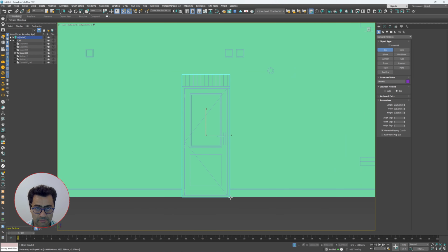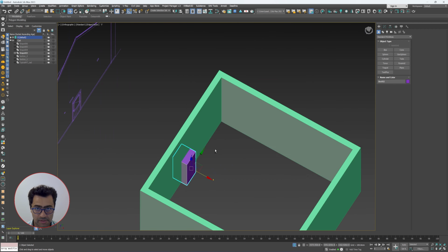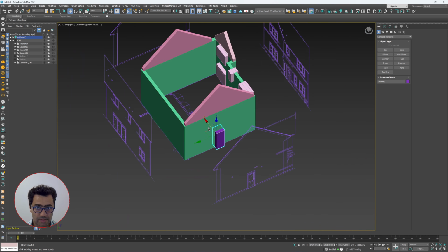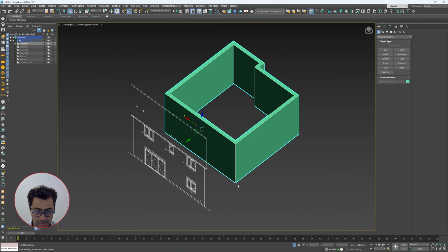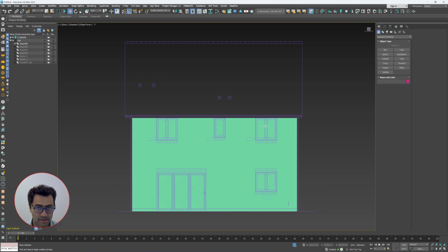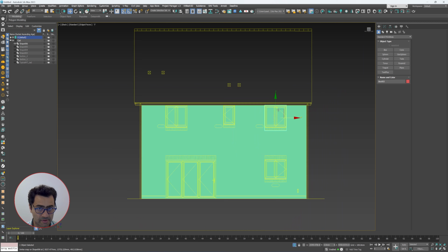Let's just create another box here. Let's just place it here. Okay. Alt Q toggle again to go outside. Just select the bits and then Alt Q again to go back in. Back viewport. If you're going to go to the back one, you can just do V and back view here. And then zoom extents all. Then let's just do the same for this bit as well.